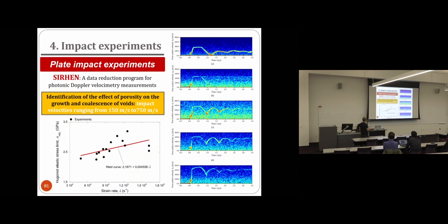And then this duration of the pulse is determined by the thickness of the flyer. Then, because of the reflection in the free surface of the plastic wave, we have this decrease of the velocity. In this case, there is no spalling because the velocity goes to zero again. If we increase the impact velocity, you can see here the same profile of the signal, okay? But here, this is not very clear, but it's there. There is a pullback velocity.